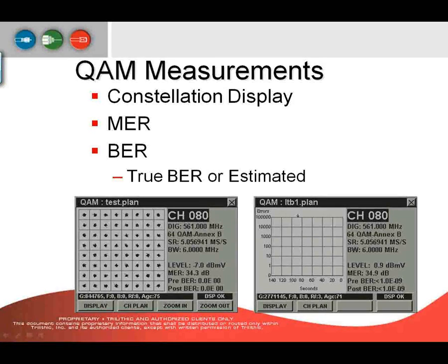I and Q streams can be represented as being in quadrature, forming a grid that offers I times Q possible states. The grid is conventionally referred to as a constellation and may be thought of as kind of like an array of boxes, with each box representing a particular I or Q symbol state.